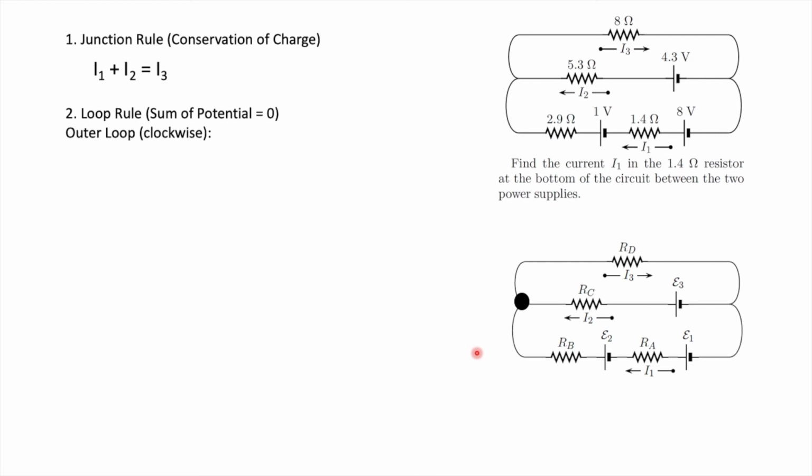Here again, I'll follow this route. Once I hit the resistor, again, this is at the positive end, that's at the negative end. How do I know? I'm assuming that's the direction of current, I3 here. And if this is the direction of current, then this must be the positive end, and that's the negative side. Positive polarity, negative polarity.